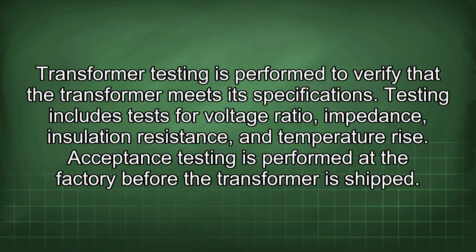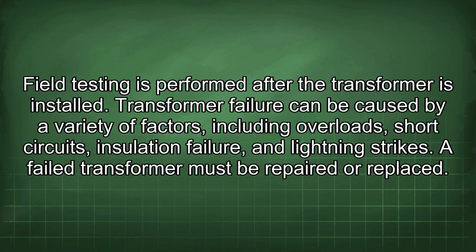Transformer testing is performed to verify that the transformer meets its specifications. Testing includes tests for voltage ratio, impedance, insulation resistance, and temperature rise. Acceptance testing is performed at the factory before the transformer is shipped. Field testing is performed after the transformer is installed.